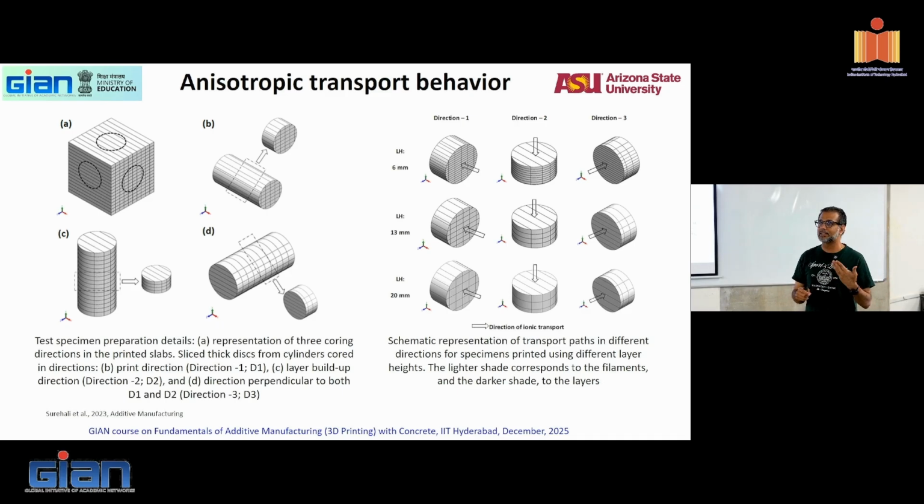People are trying to understand and realize it now because you're applying an extremely high voltage over 6 hours. You have so many heating effects, and resistance or conductance is a function of temperature. You're getting so much Joule heating, and temperature changes the microstructure of concrete. When you have a very dense concrete with a very dense microstructure, which means the resistance is very high, the temperature also is very high. When you get to about 80, 90 degrees Celsius, you will have microcracks. So it's actually not a good test.